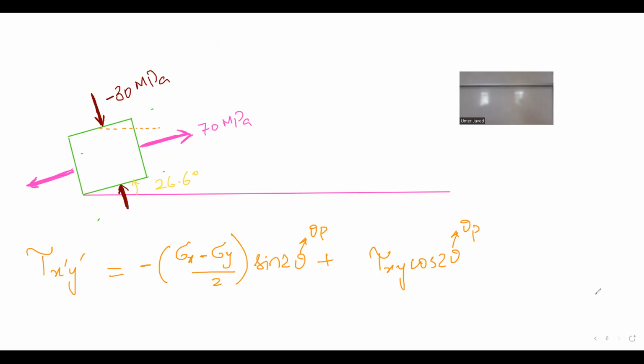My stress is equal to P over A. And then I used to say, what will be the yield stress of this object? And am I below the yield stress value? And I was feeling happy about myself. Turns out that there are planes that exist on it that will have actually a normal stress, possibly way larger than what I am exhibiting this to.